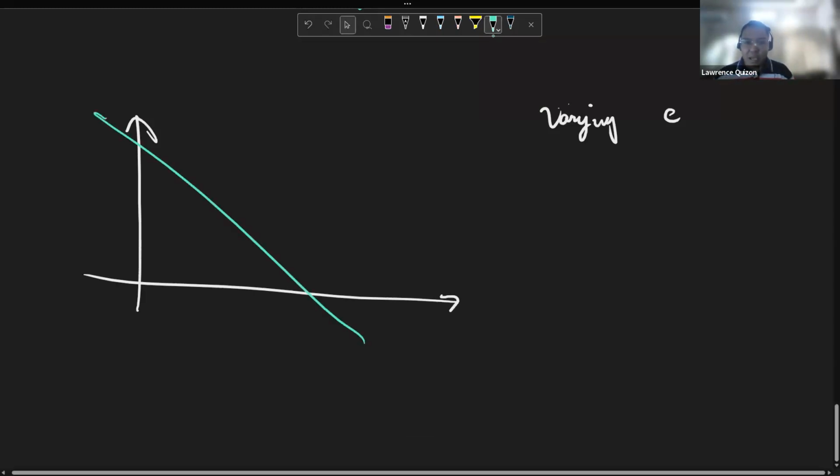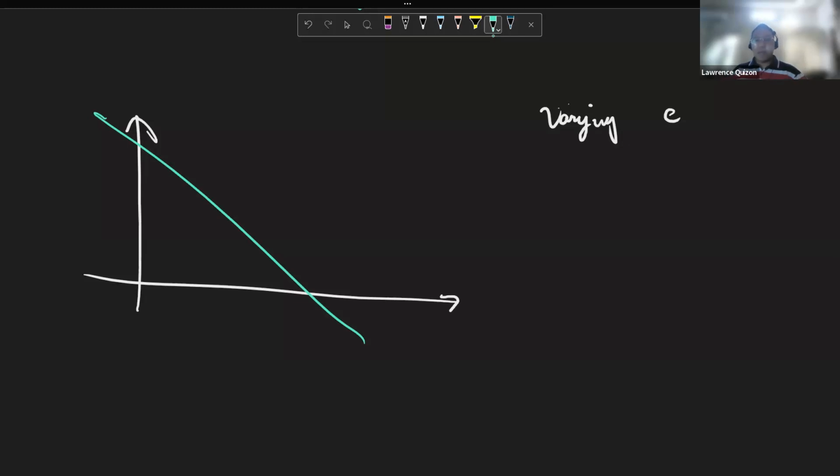When you have a lab class where you design amplifiers with BJTs, I don't recommend changing the transistor. Change everything but the transistor, because it's very hard to choose one, since you can't see from the outside what the value of beta and such is. And of course, they're all 2N3904.